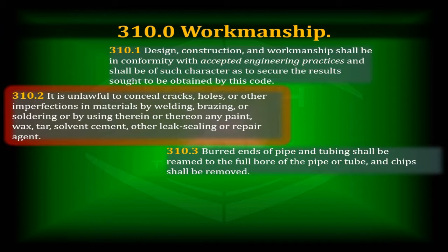Anytime that you're cutting pipe, whether it's copper pipe or PVC pipe, both of them have their issues while cutting. When you cut copper, oftentimes we tighten the cutter wheel too tight, and when we do that, it rolls the inside of the copper as we cut it, and so it changes the diameter of the copper, makes it a smaller internal diameter, and that creates turbulence and such.